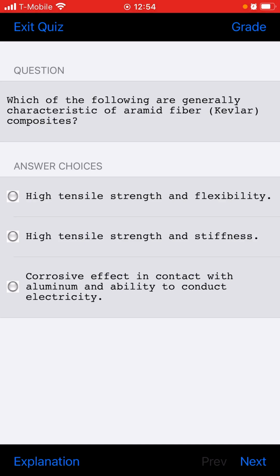When straightening members made of 2024 T4, you should straighten cold and reinforce.